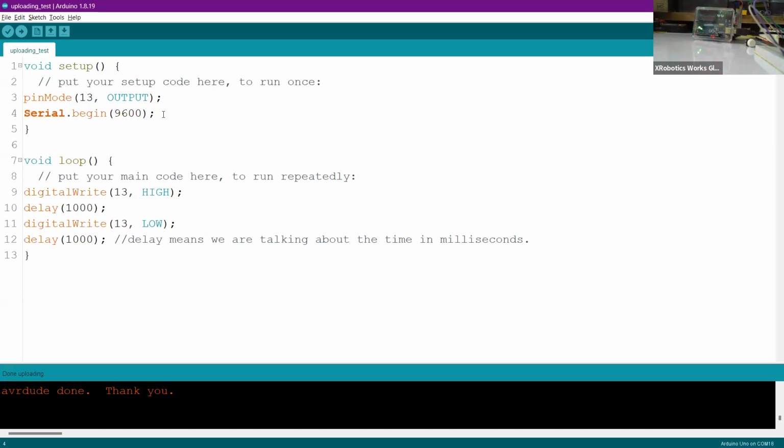So the Arduino board has a limitation of communication speed, but if we talk about the NodeMCU and others, they utilize 115,200 bits per second to communicate with the computer system. Even for the Arduino board, we can increase that value, but that is somehow limited for now.